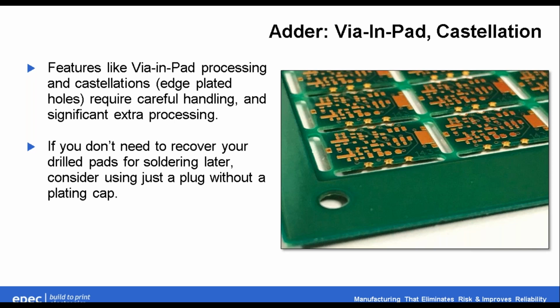And the reason people use it is sometimes you might want to take a little board like this and piggyback it onto a larger board or a very simple board underneath. So you get the extra features that are on this small board, and they're actually connecting in at these castellations to the other board. You might have surface mount pads where each of the castellations is. You put this board down against those surface mount pads, and then you solder using these castellated holes. You solder to the surface mount. Now you have a little board with extra function piggybacked onto the top of your main board. That's largely what it's about.